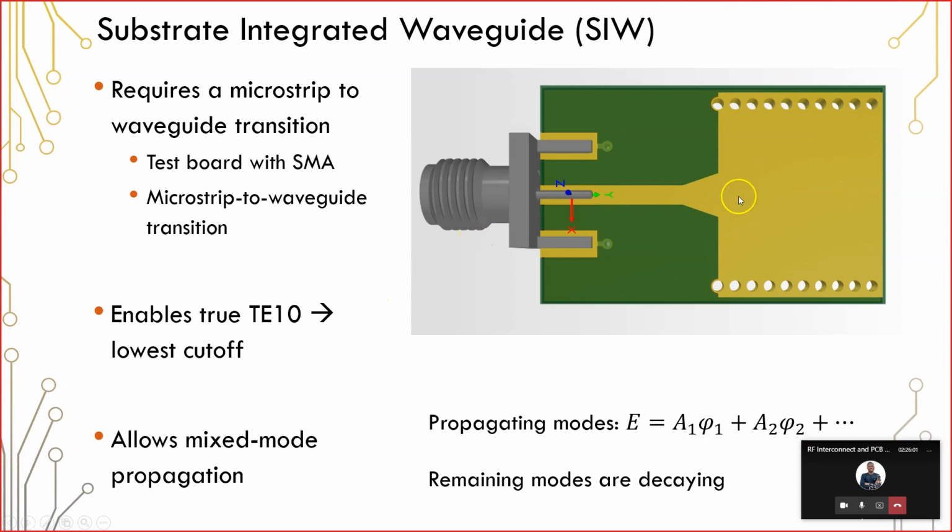But this particular structure is very wide. Now, there are actually references that you can find that will help you calculate this taper length so that you can size this taper appropriately, and you don't have to actually worry about calculating the wave impedance inside of this structure.